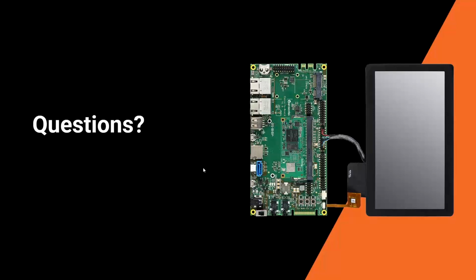By default, also for the 6UL, it is actually 32, but to save half of the memory in our implementation, we use 16 bits instead of 32. So this patch is only required for LVGL when you use the 6UL. In any other case, it's not required.